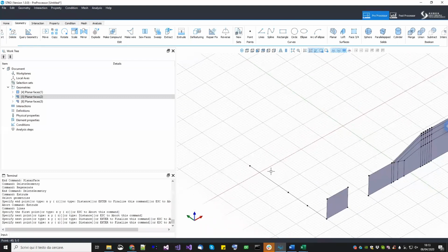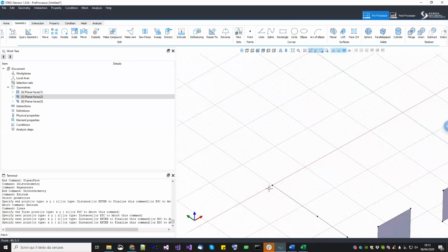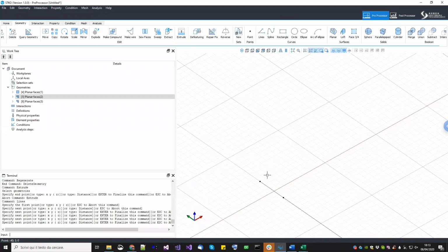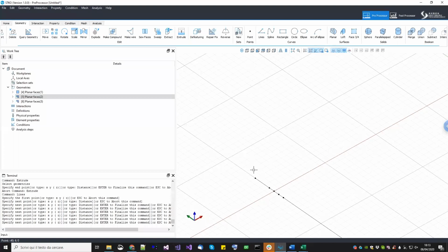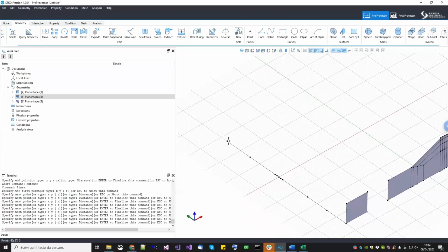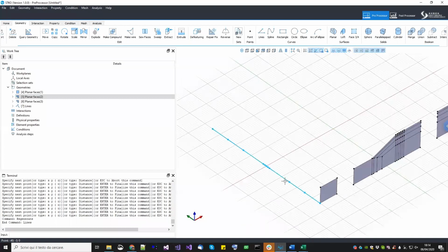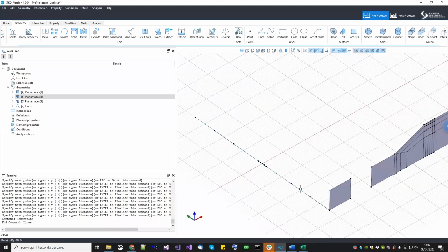Okay, and then we have 30 meters of soil here, divided in the first 15 meters. Then we have 4 steps at 1 meter each one. I need them just because when I put the superstructure, I need this subdivision. Then once again, another 13 meters. Then another 10 for the spacing. And the last 10 meters for the last free field column. Okay, now I have my profile for the extrusion, but actually here I don't want to put anything,